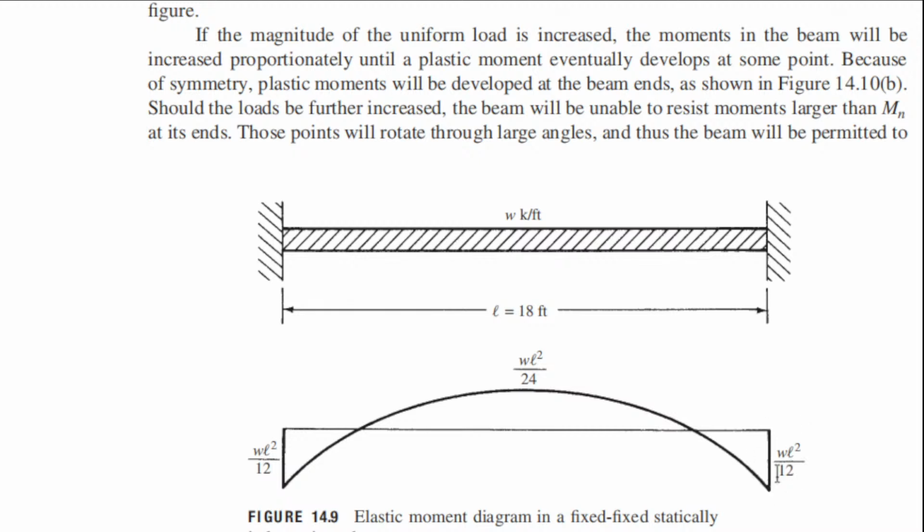As we go on increasing this value of load, this moment will go on until it reaches the nominal load. It will not go over or greater than Mn. Okay? The maximum that it can resist is Mn. So can you imagine what's happening?